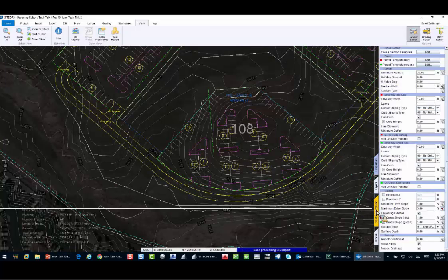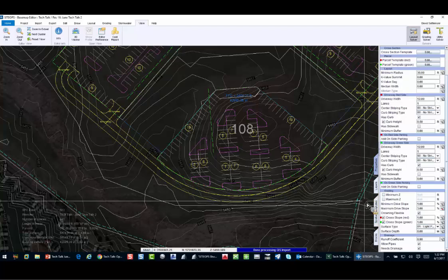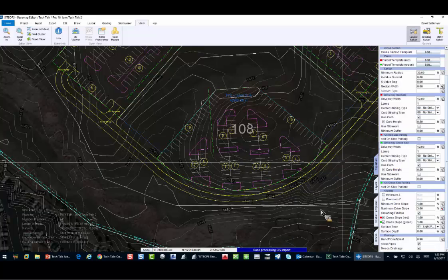Now, SITEOPS for a wall, let me go ahead and just put this out there for you. It is not going to just throw a wall up for the heck of it. It is going to throw it up because it is the cheapest option, and it is going to try to minimize that wall. Now, there's ways to go back in and force SITEOPS into having a wall if that's what you want, and making it the size you want. You have all the control over that. But typically, again, that is most likely not the most optimized way of doing the project.